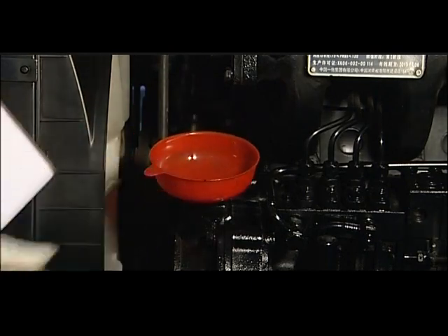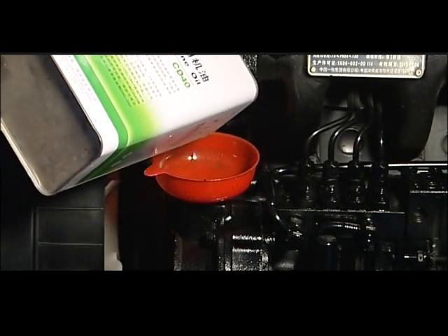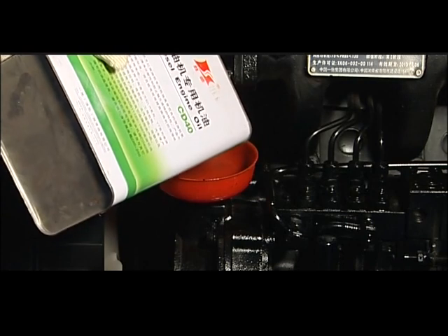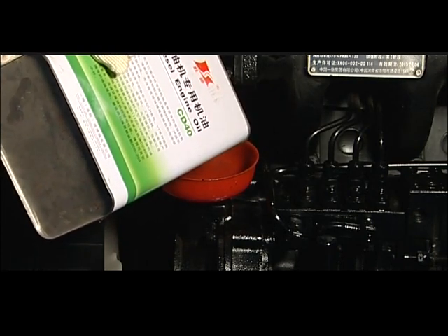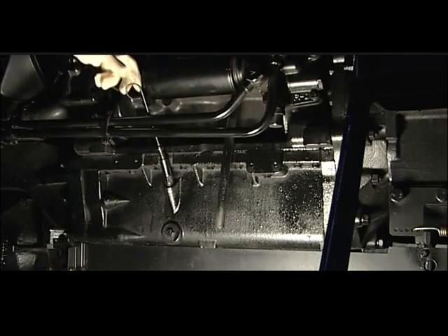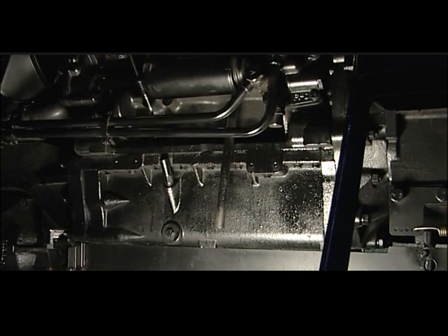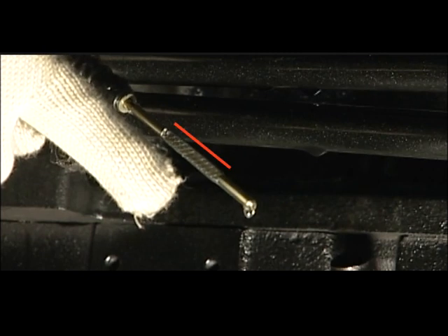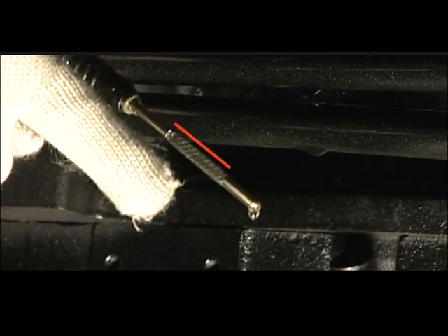Refill with new oil from the engine oil filling orifice. Pay attention to refill oil as required. The refilling amount shall be within the upper and lower limits of the oil stick. The test result within 5 minutes after refilling is used as the norm.